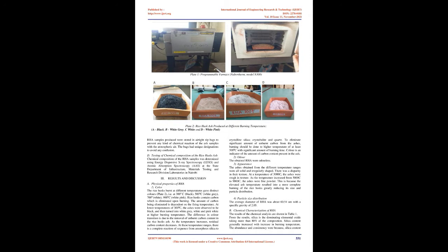Jaya et al., 2013, did a study on silica phases of gray, white and white-pink ash. Results from XRD analysis show that the amorphous phase was exhibited in the gray and white ash, while the crystalline phase was in the white-pink ash. Therefore, to produce silica in amorphous form or crystalline, two factors are important: incineration temperature and time.